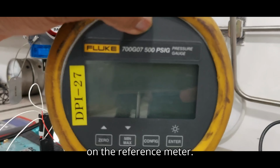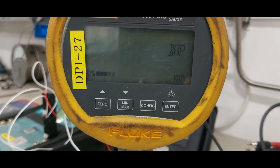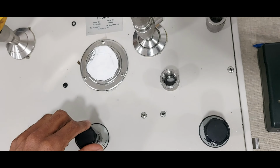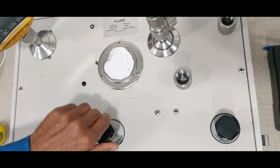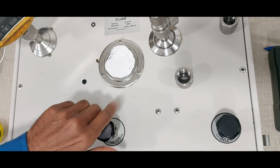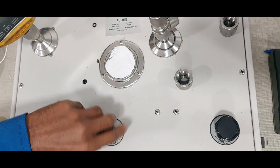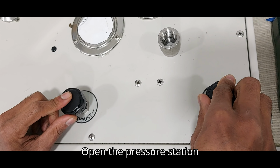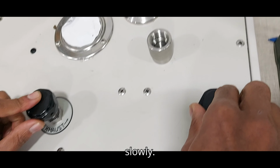Next, power on the reference meter. Set to 0. Close the vent line. Open the pressure station slowly.